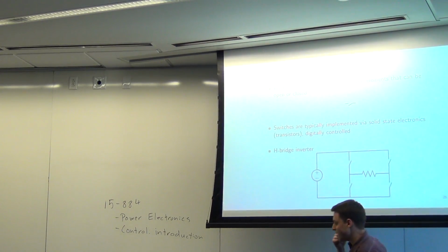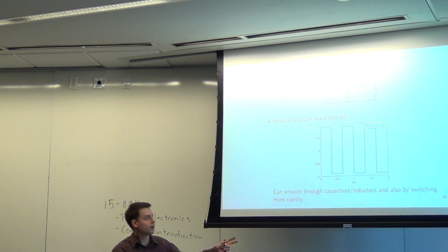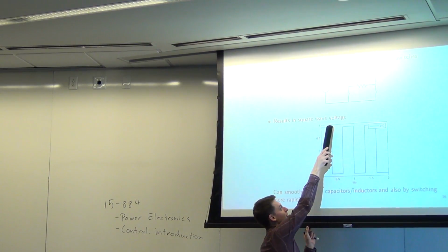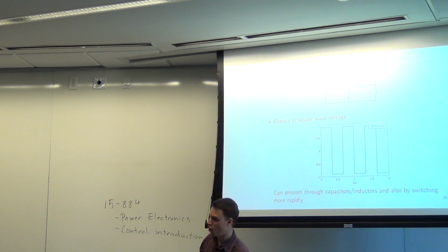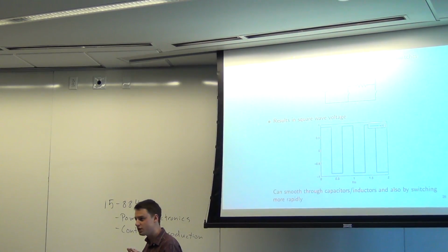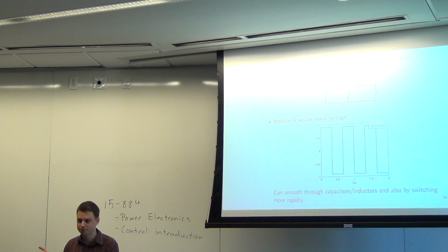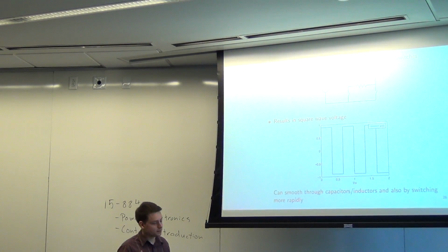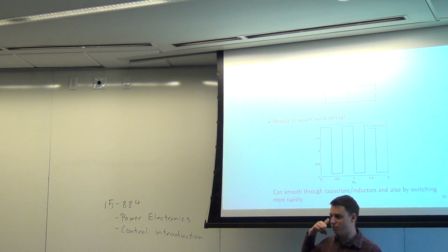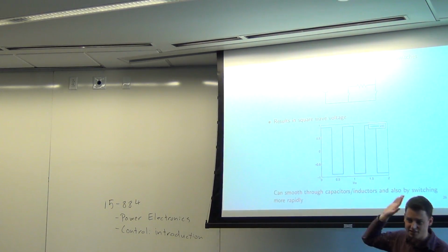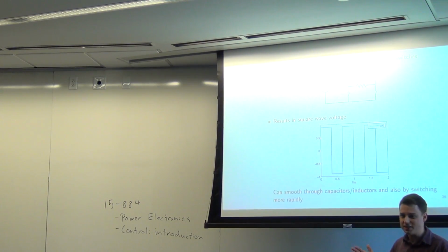And that might not quite seem like AC power, because it doesn't look like AC power. It looks like this, right? Sometimes you have a maximum voltage there, and then the maximum voltage is the other way. Because all we're doing is opening and closing the switches to make the element see current in one way or the other way. But in some sense, this is an AC signal. It's just not a sine wave. It's a square wave. But it is an alternating current signal.